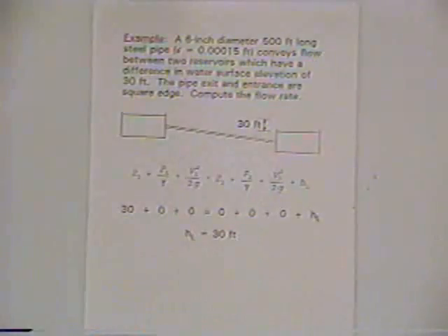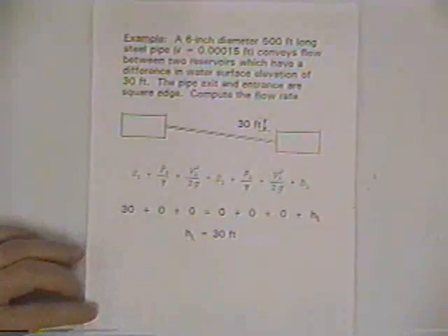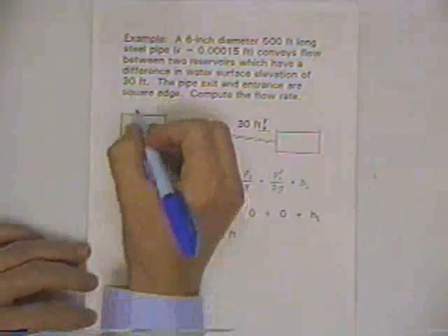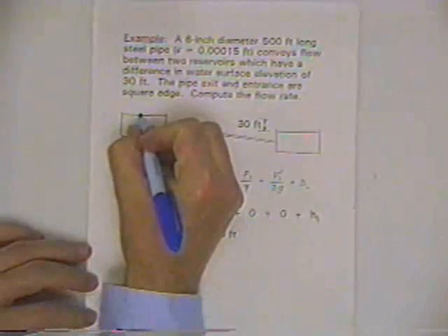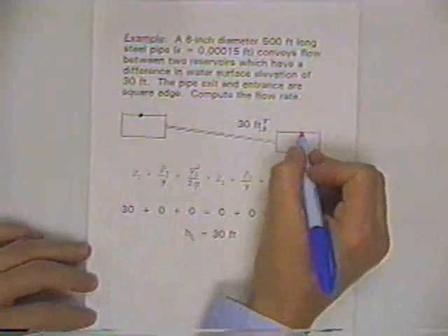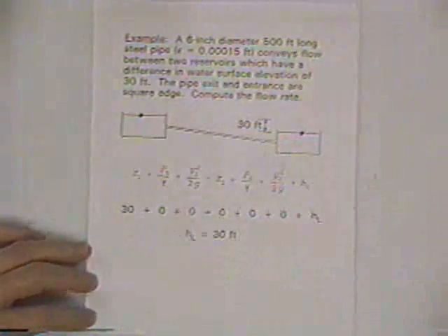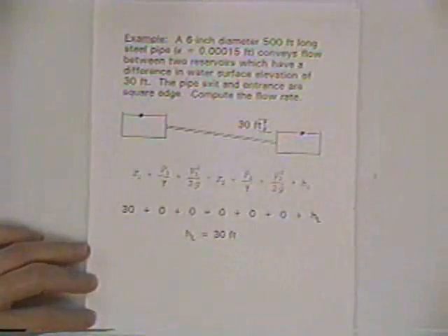And so we can apply the energy equation, another application of the energy equation. It's certainly a workhorse in fluid mechanics. In all energy equation applications, we've got to use a little bit of ingenuity to pick out a couple of points that have significance, and the significance is usually because we know certain values at those points.